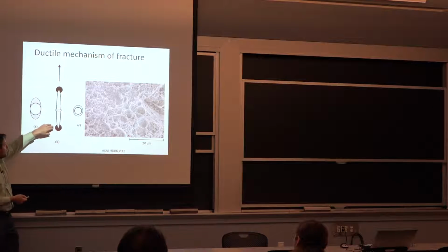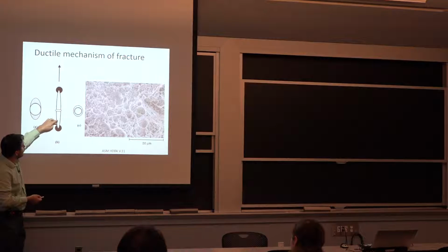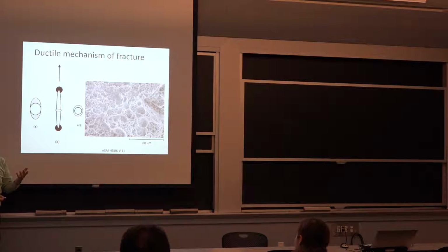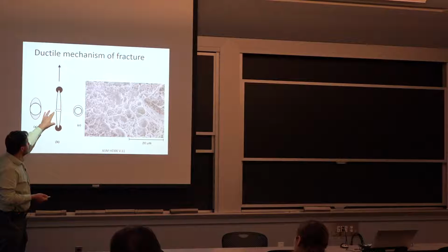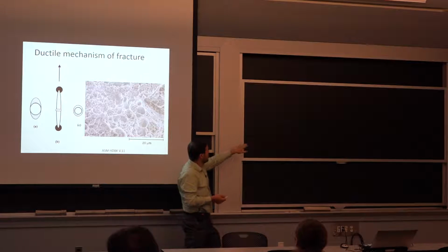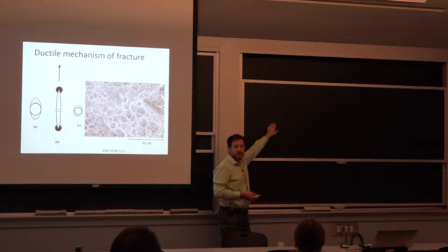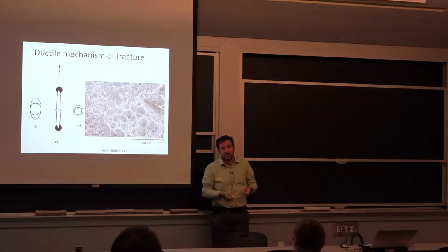You start deforming it. It debonds at those locations. It stretches. You can see that if we started in contact here, when we get to this point, this is where we get our 200% strain. The material becomes about twice as long before it fractures. That's the ductile behavior. Now, why it breaks is not so much because of this stretching. Well, there's a little bit of this, but the other aspect is it runs against another little microvoid that was next to it, and now you only have a little ligament to hold the entire load, and it necks.